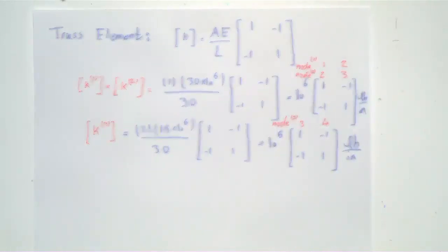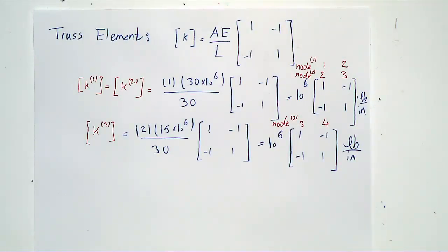All right, so before coming up with the global k matrix, the first thing that we need to figure out is the size of the global k matrix. Can anyone remember how we calculated the size? Exactly. You need to look at how many degrees of freedom we have here. One displacement per node, so in total 4 degrees of freedom.